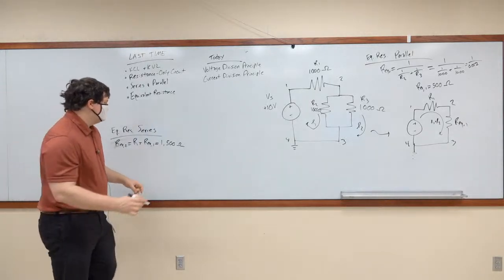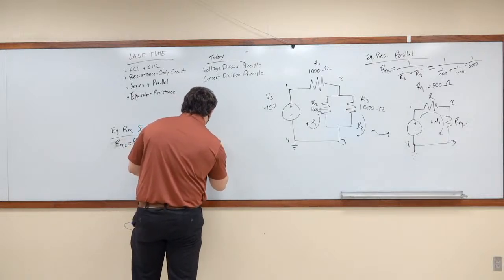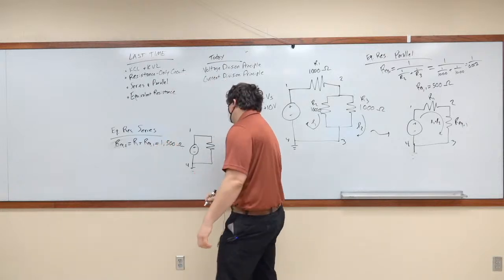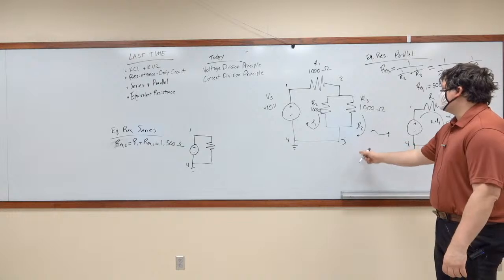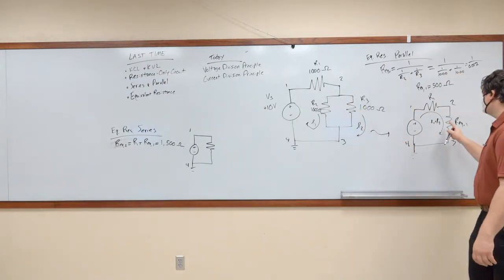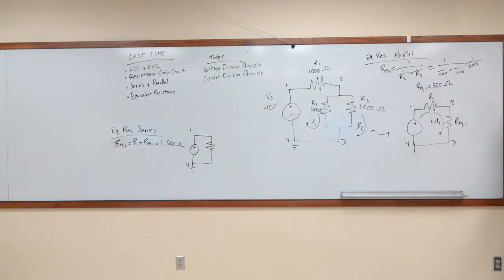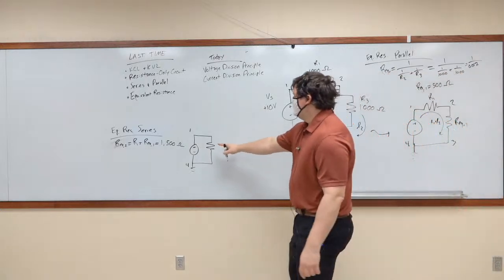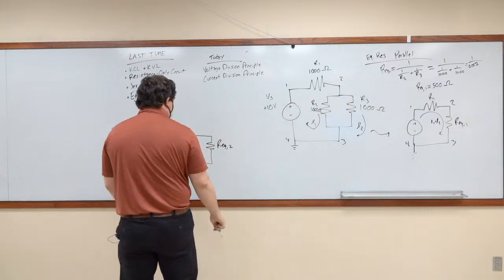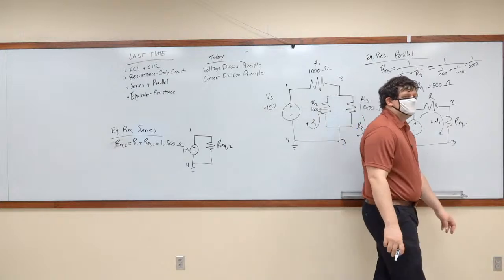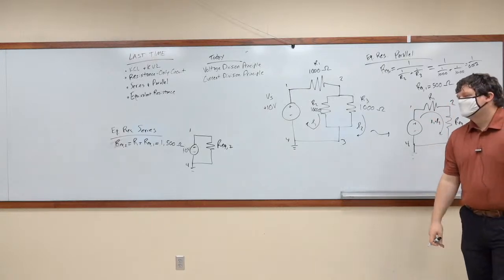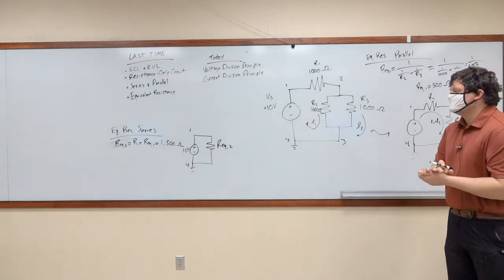And now what we've done is we've created a brand new circuit that looks like this. This is 4, it is still grounded. This is 1. But we have removed node 2. Why did we create a node 3? Node 3 and node 4 can combine. But when we combined these two here, we got rid of node 2. Node 2 is somewhere in the middle of REQ2. But now that we've done this, we know we have 10 volts. We know that we have a resistance of 1,500 ohms. We can calculate what that current is. So, how much current is leaving the battery right now?